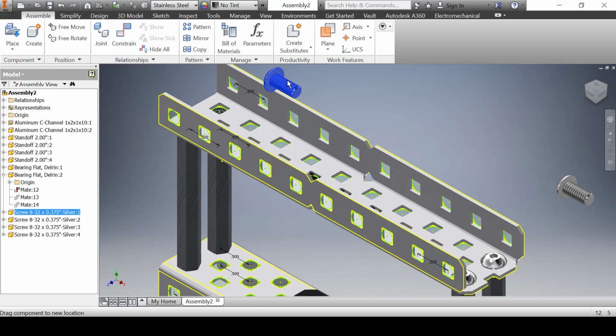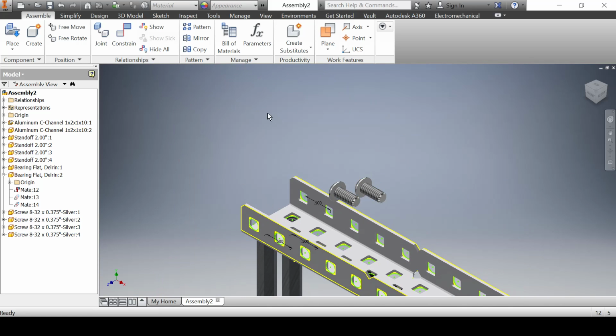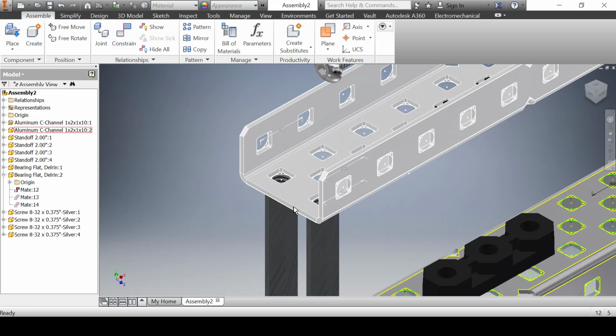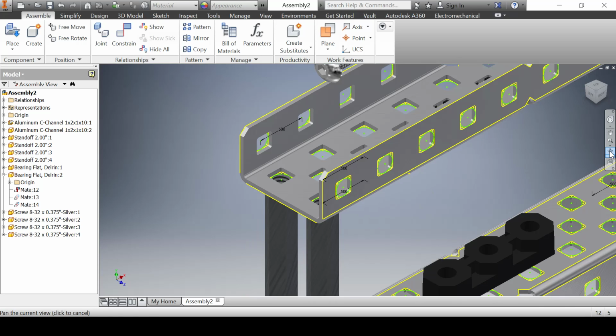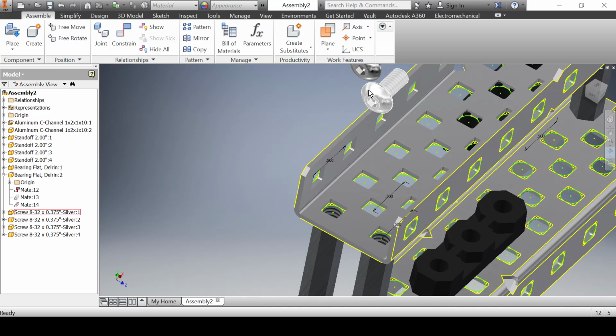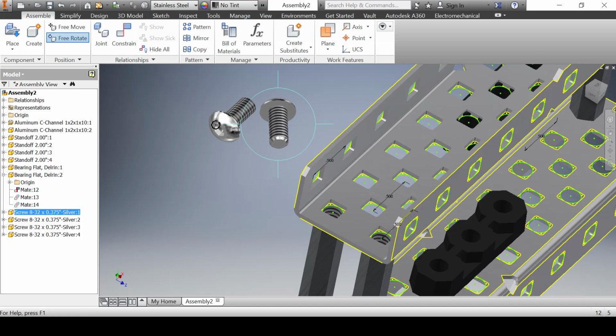Alright, we're going to move our screws over here. Do the same exact thing, but this time, since I can't see both those holes, I'm going to click on this edge of the cube. It's going to rotate my view, make it a little easier to see those. And if you want to make it even easier, you can use that orbital tool from before and orbit it just to where you can see it. Now I'm just going to rotate these guys to face me.